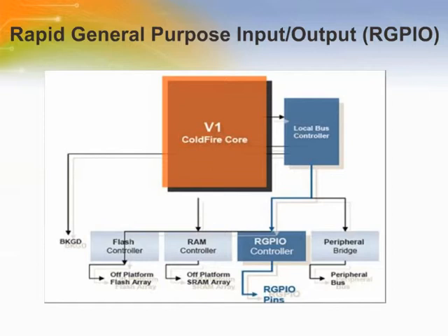This module is a memory mapped device. The data registers can be accessed directly via the alternate addresses which support set, clear, and toggle functions using simple store instructions.